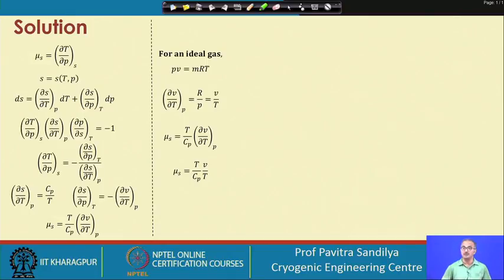ideal gas. Now, what this means, as I said in the lecture, is that in case of isentropic expansion, even an ideal gas will undergo a temperature change, and because μS is always positive, on expansion the ideal gas will always cool, unlike the case of the isenthalpic expansion when the gas may either get cooled or heated up. The isentropic expansion will always result in cooling.